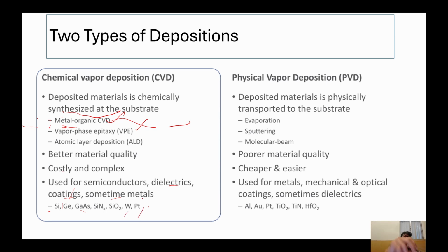Tungsten is very hard to deposit through vapor phase deposition techniques, or the physical vapor deposition technique, because tungsten has a very high boiling point. To deposit tungsten you have to go to very low vacuum and very high temperature, and you also need a material that can withstand that temperature and not get evaporated, in which we can fill the tungsten.